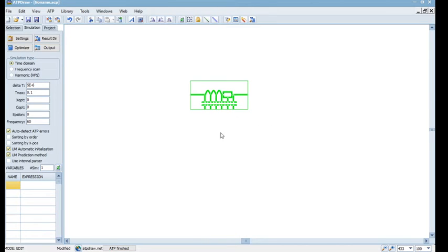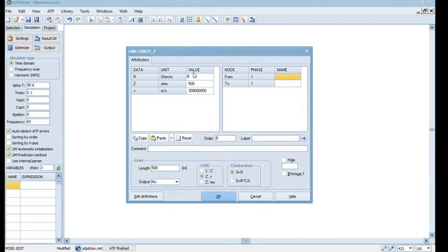So you'll see a two node kind of element wherein you have this illustrative distributed element LC thing. When you double click over it, you'll get this kind of functionality. So you have length, outputs, inline, like what all parameters you can specify. If I say L dash C dash, you can specify those. If I say Z and V, propagation and characteristic impedance, you can specify that. Or if you want Z and tau, which I hope you can relate to, you can specify these things.